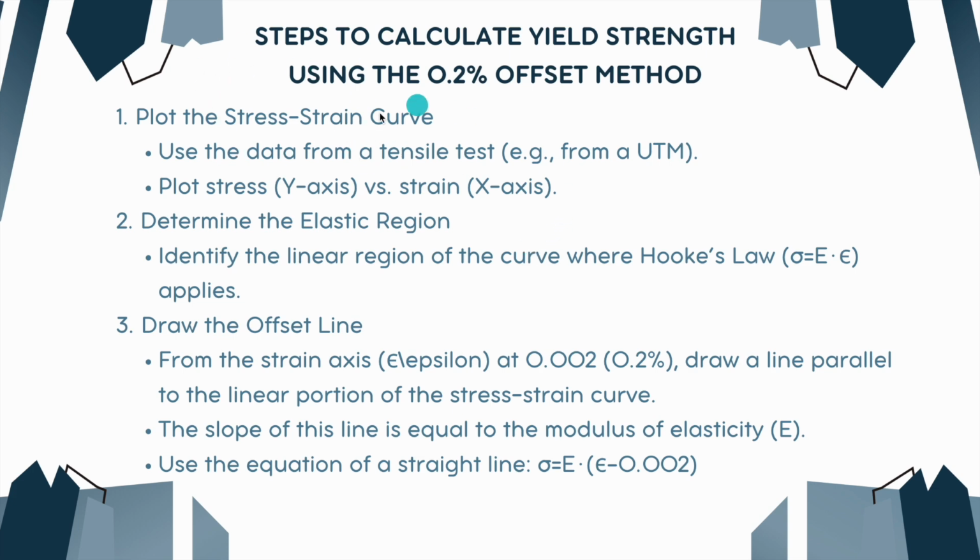We plot the stress strain curve at first, using the data from the tensile test from a UTM, and plot stress on the y-axis and strain on the x-axis. After that we have to determine the elastic region.